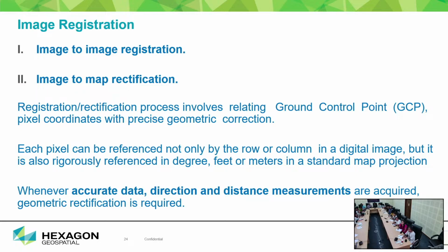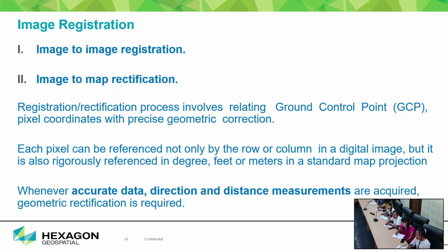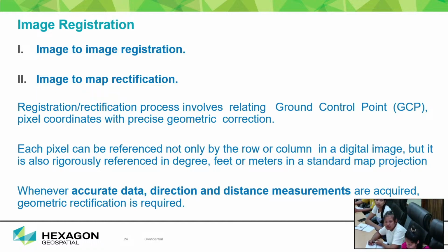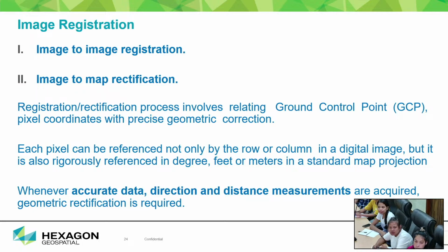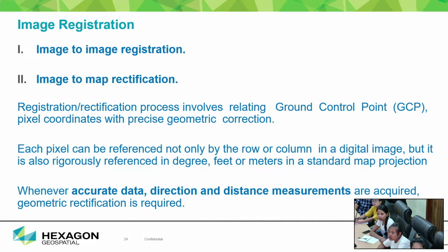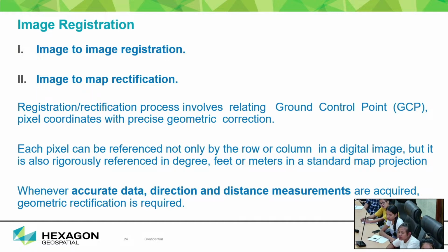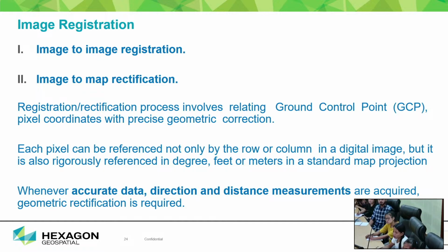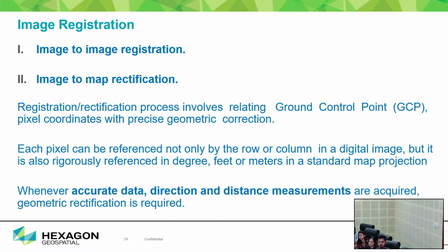Okay, but we have to check whether these features are matching, and if not matching, then we have to go for the image registration, and again do the georeferencing and whatever process we are doing. So ERDAS Imagine, here I want to mention, for this purpose ERDAS Imagine has automatic auto sync. You just give your input of the two images, ERDAS Imagine will do the rest of the work.